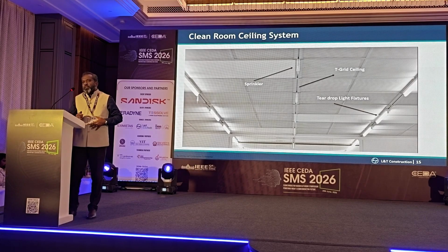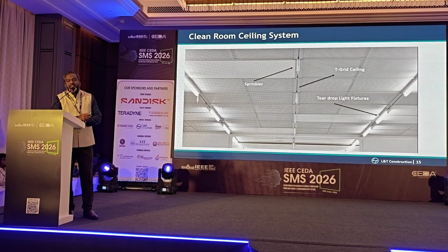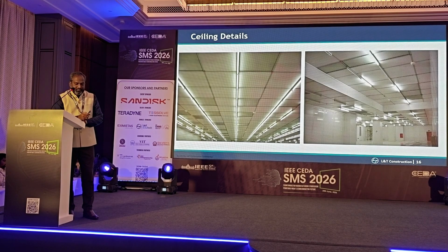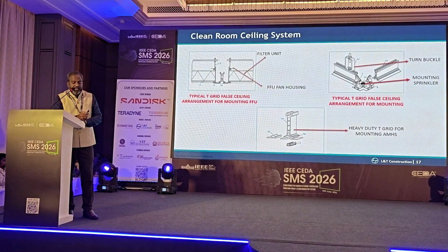That's a typical false ceiling of a clean room. Everything gets integrated in the clean room false ceiling. It needs to be clean, right? You see the light getting integrated there. Sprinkler you would not be able to see because that gets recessed. You've got a lot of gas detection system that goes up there. We are talking about a lot of hazardous gas chemicals. So just a view of how these clean room false ceilings would look like.